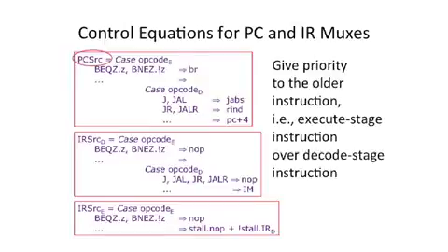We have something which is redirecting for a jump out of the decode stage. And then we have these signals here, which are coming out of the execute stage, which is strictly farther down the pipe. And this needs to take precedence over that. So if you have a branch which is directly followed by a jump, the jump's going to be sitting there trying to swing the control on the PC select mux, the next program counter mux. And you can't let that happen. You have to let the branch that's actually executing take precedence over that. That's really what we wanted to get across from this. You'll see that similarly here, the branch takes precedence over the jump and link for the other control signals.